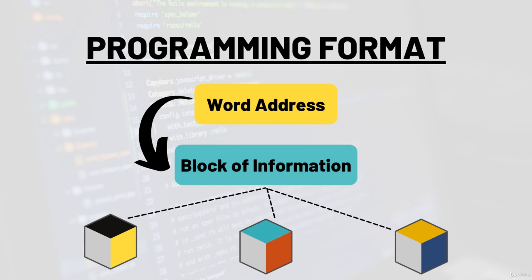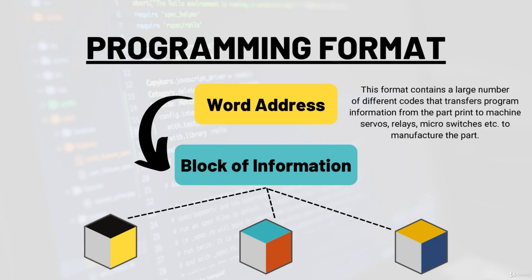Word address is the most common programming format used for CNC programming systems. This format contains a large number of different codes that transfer program information from the part print to machine servos, relays, microswitches, and many more, ultimately to manufacture the part. These codes are in a logical sequence called a block of information. Each block should contain enough information to perform one machining operation.